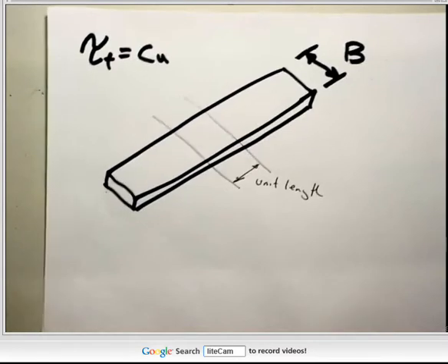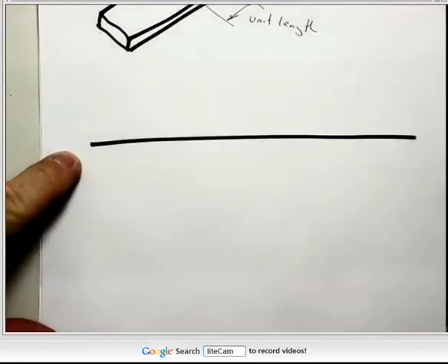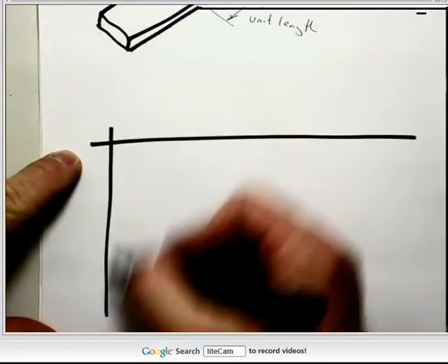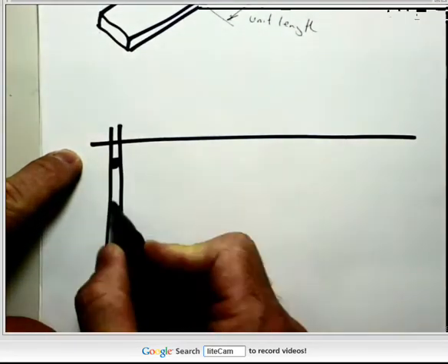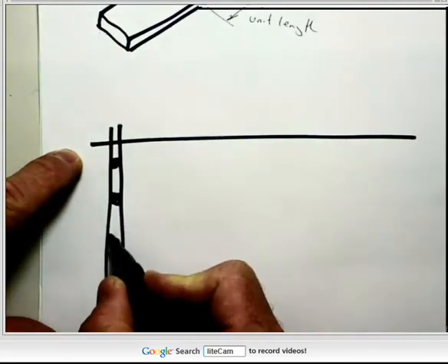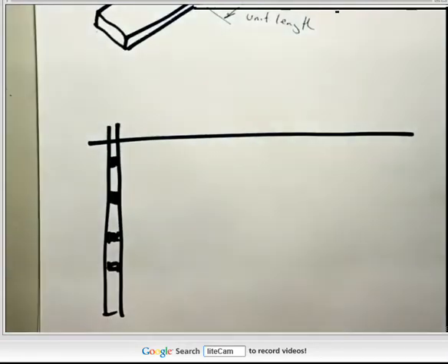Okay, we're actually going to consider a situation where the undrained strength, so we've got a site like so, and we put down a borehole, and we're going to take a number of samples from various depths, like so, and we're going to plot the Mohr circles of failure.